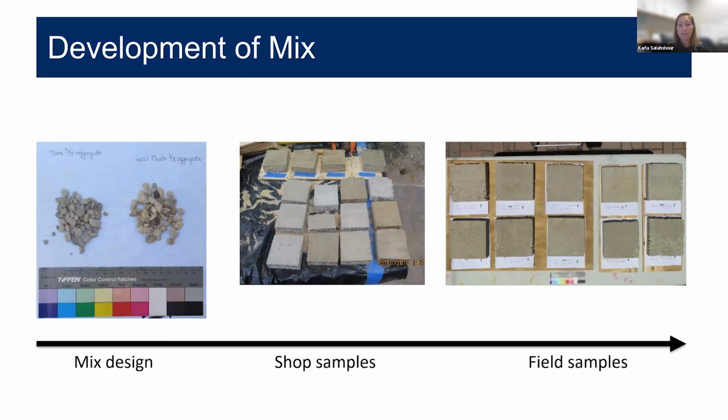So what we aim for is to match the materials as best as we can. Note that it's hard to match a poor quality concrete. So in moderate climates, poor quality concrete can actually last a long time, but in freeze-thaw climate, like where I'm in Ohio, poor quality concrete really doesn't last very long at all. Good quality concrete is obviously much easier to match. And so regardless, our repair materials are always going to be slightly different when we design a repair mix for a historic structure.